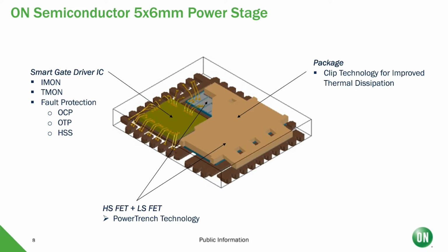And the driver IC's job is not just to turn on and turn off the low side FET. In our new generation of power stages, we have incorporated a few smart technologies into our driver with several different features. One of them is to provide a current output that can go back to the controller. Basically, this represents how much current the power stage is drawing or supplying to the load. And each phase of the power stage is going to report this differentially back to the controller.